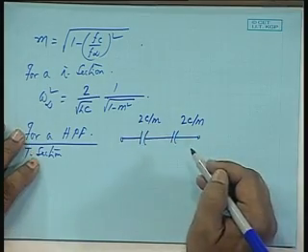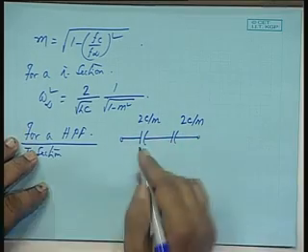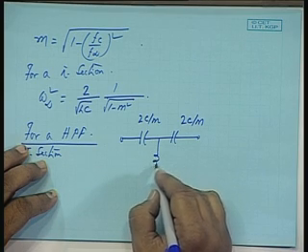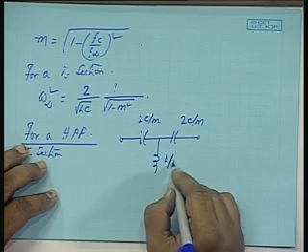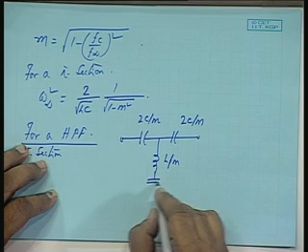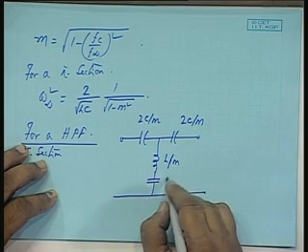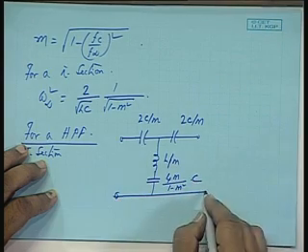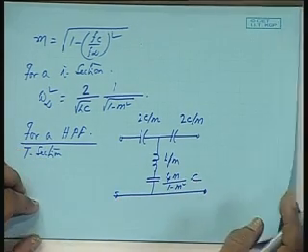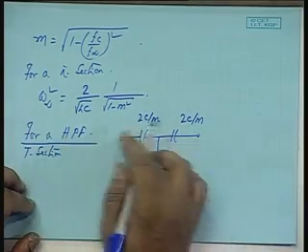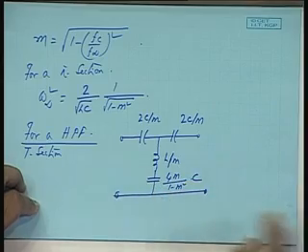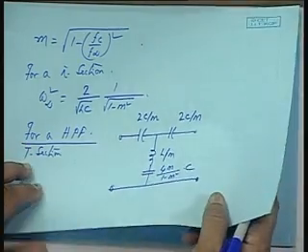So, corresponding reactance, the elements will be capacitive elements of these values, and this will be L by m and a capacitance of value 4m by 1 minus m square C. For a high pass filter, these elements will be capacitive, these will be normally inductive. So, I have an additional element C when we take the m-derived filter.